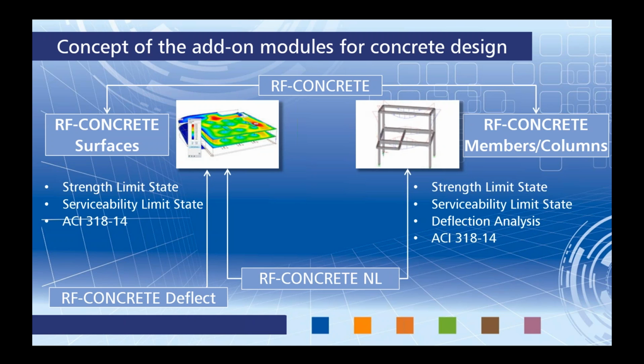Now our other program, RF-CONCRETE Surfaces that you see over here on the left, is for any type of slab element, surface element, walls, plates, shells. And here we can also do a strength and serviceability limit state design according to the ACI 318. We also have several international codes for all of these modules as well.